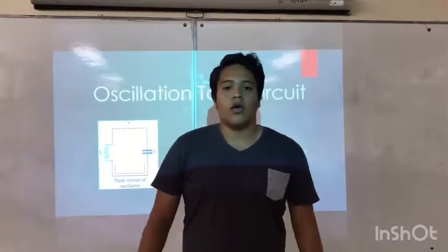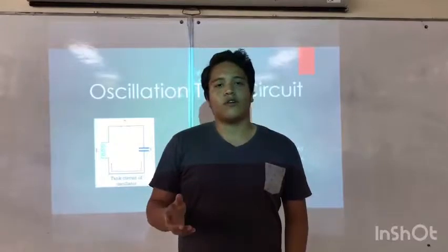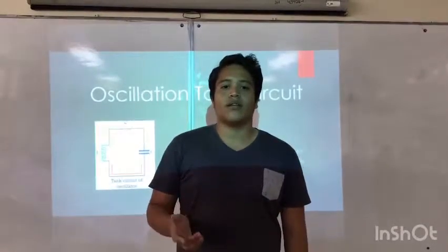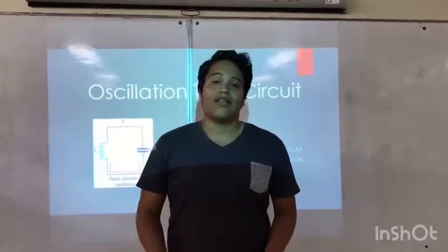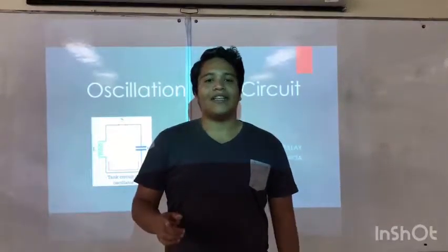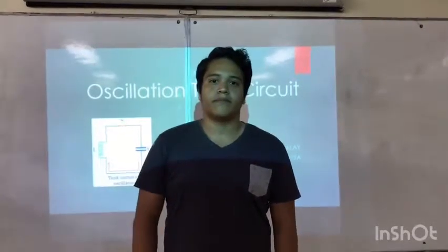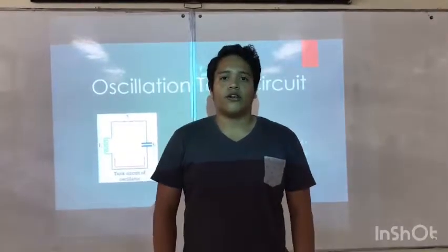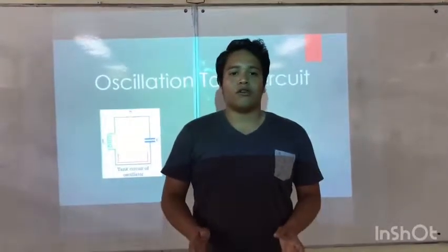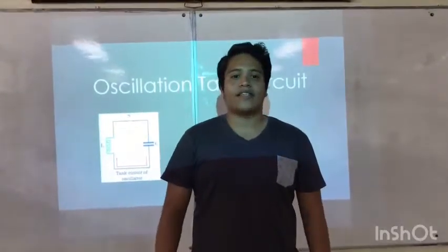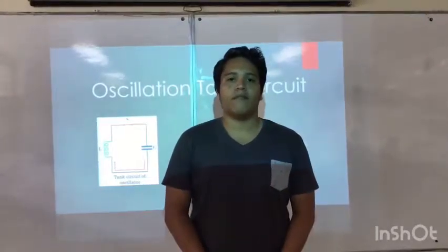Oscillations work because they overcome the loss of the feedback resonator circuit, either in the capacitor, inductor, or both in the same circuit, by applying DC energy at a required frequency. In other words, an oscillator is an amplifier which uses positive feedback that generates an output frequency without the use of an input signal.